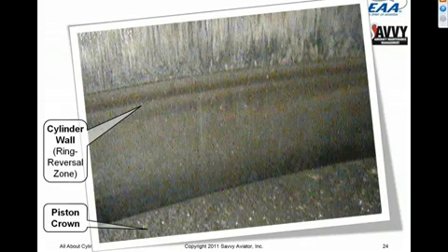This cylinder, you can see the cylinder walls have no crosshatch left, so they have definitely worn quite a bit, but the walls are in pretty good shape nevertheless, and this particular cylinder was reading 75/80 compression the day I took this picture.